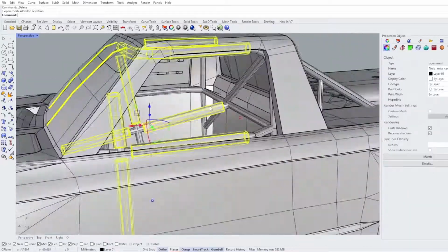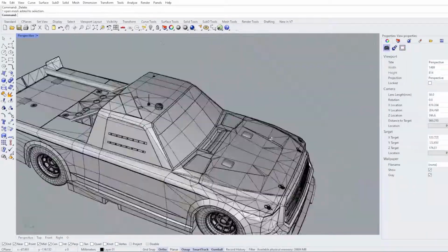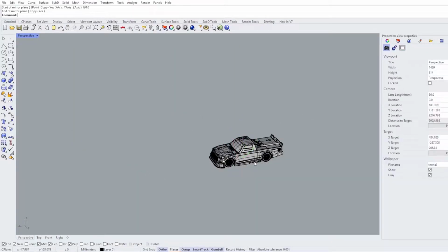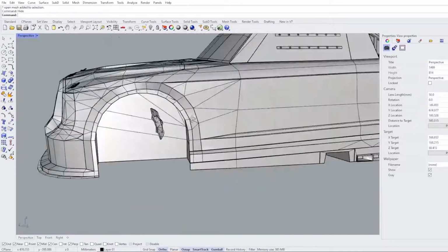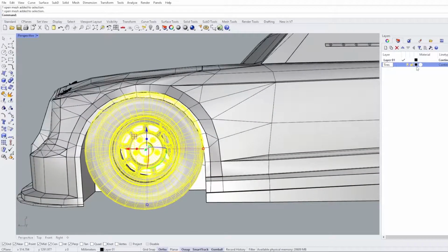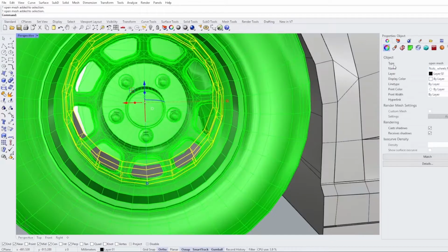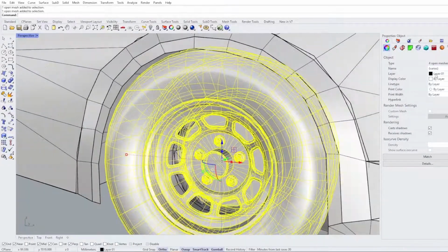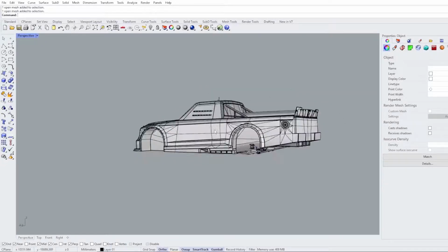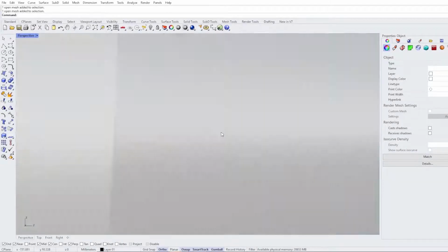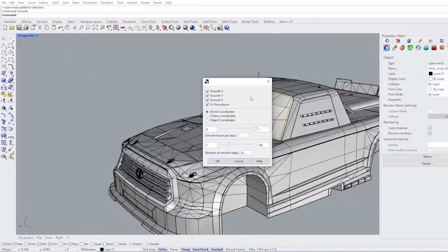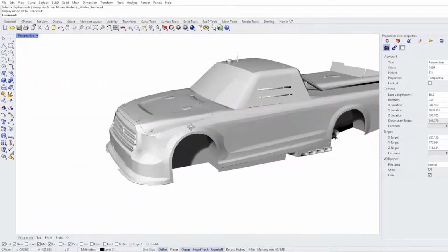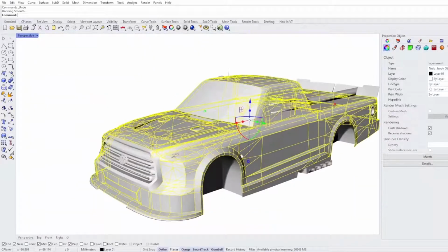So the program that I'm using to clean up this model is Rhino 3D. It's my program of choice, really. That's the one that I feel most comfortable with. But as I mentioned earlier, the tires and the windshield were the big ones that I noticed were not going to be printable. So right here, I just started taking out some of those and turning off the layers that I knew wouldn't totally work. And I just started playing around with the polygon count as well.